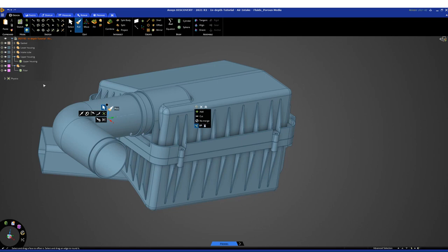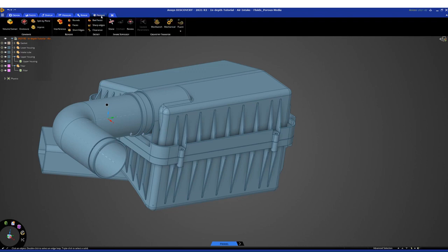So what we will do now is to extract the fluid domain from this. One way to do that is by using this volume extraction for watertight geometries, but there are also other ways to do it. If you have leakages that you cannot handle by closure, you can do Boolean extraction. But now we will focus on this volume extraction tool, which I find here under Prepare.